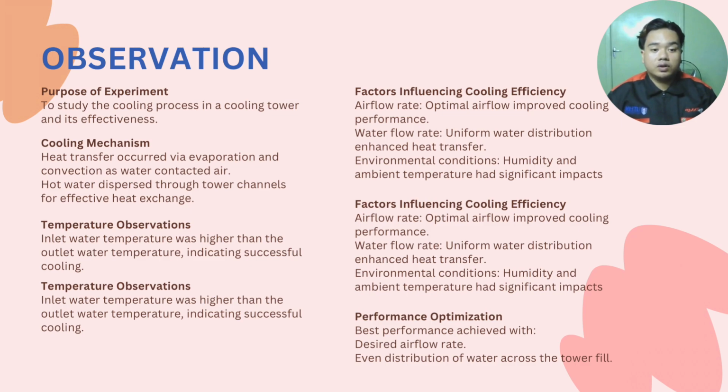It was also found that the inlet water temperature was slightly higher compared to the outlet water temperature, which shows effective cooling has been done. Other parameters like the rate of airflow over the heat exchanger, the rate of water flow, the humidity, and the temperature had a strong impact on the level of cooling. Cooling performance was better at the desired airflow rate and an evenly spread layer of water over the tower fill. That's all from me. Thank you.